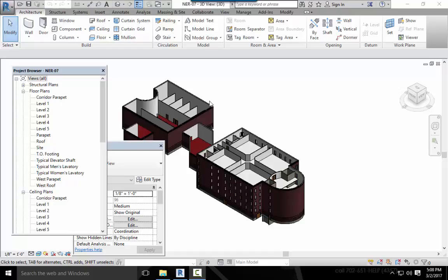And I'm going to tell you that code tells you a flat roof has to have a slope of 1/4 of an inch to a foot minimum. I typically design them at 1/2 of an inch to a foot minimum, because by the time the contractor actually installs it, you're lucky that you end up with 1/4 of an inch to a foot minimum on a flat roof. It's just something to take into account.